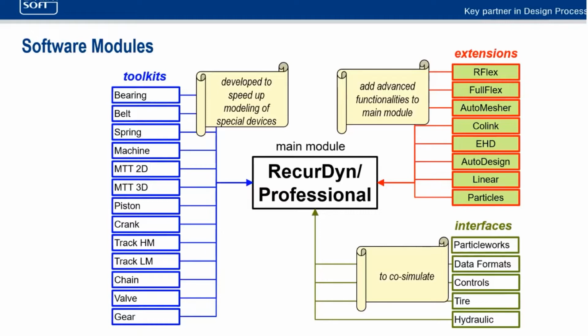You need to define contact between the links and the ground and maybe other components. So RecurDyn has basically automated that entire process, where you can define, hey, I need a sprocket here. It's got these parameters. It'll make the geometry for you, and then you connect this sprocket and these four road wheels, and that's going to define the track system, and it'll do the wrapping and placing of all the links for you and all that stuff.